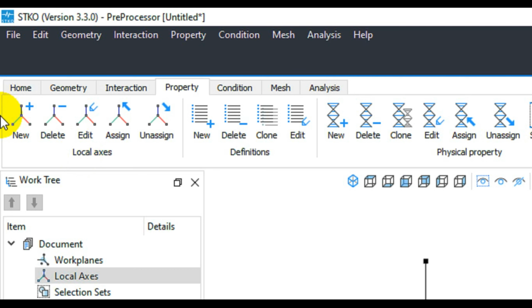They ensure that the geometry and material properties are assigned correctly with respect to the physical structure being analyzed, and this alignment is essential for accuracy because it represents the behavior of the element in your FEM model. For loads and boundary conditions, properly aligned local axes ensure that applied loads, constraints, and boundary conditions are correctly oriented with respect to the elements. Misaligned local axes can lead to inaccuracy in the analysis results. Also, for the interpretation of results, the local axis, as I defined previously, is important.